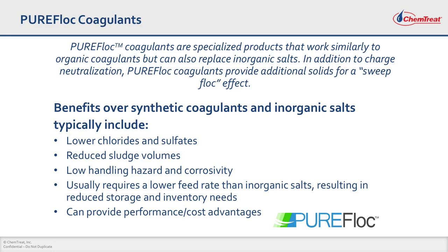And because you're using less of it, you are actually impacting the amount of sludge that you're generating. There are low handling hazards in using this product because it's not an inorganic, and the feed rate is much less than you would see with inorganic salts. And of course, the performance cost advantage over organic coagulants is good.